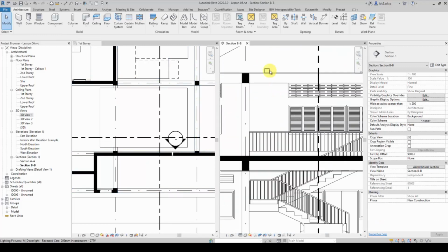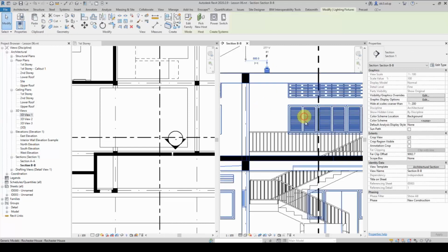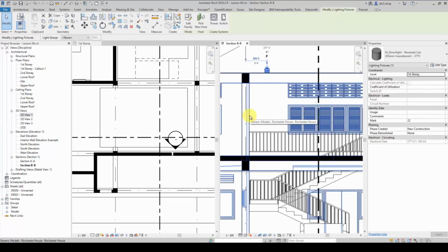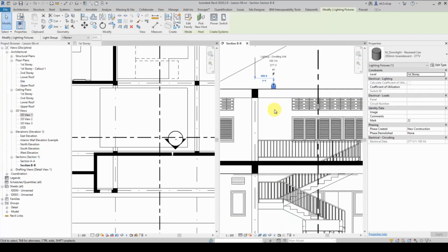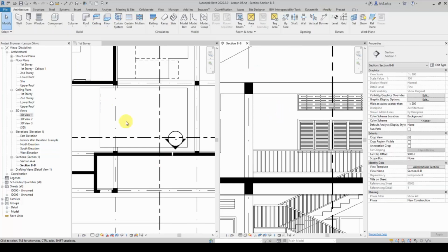Thank God it's inside already. I'm just going to close this 3D view for now and then zoom out. Okay, so that's how we place ceiling components. Again, remember this one: in general, quite a lot of ceiling components are ceiling dependent. So we need to create a ceiling board first in order for us to be able to add in the ceiling fixtures and components.